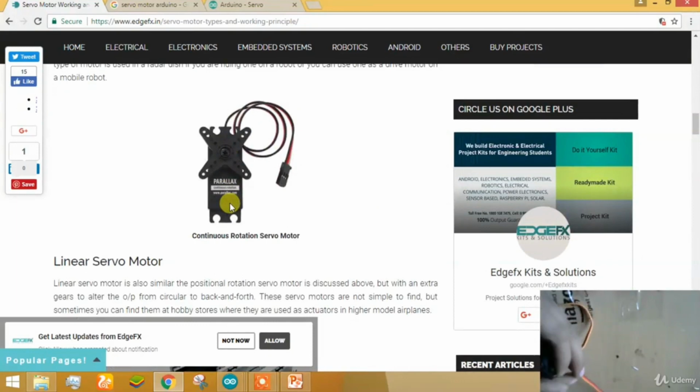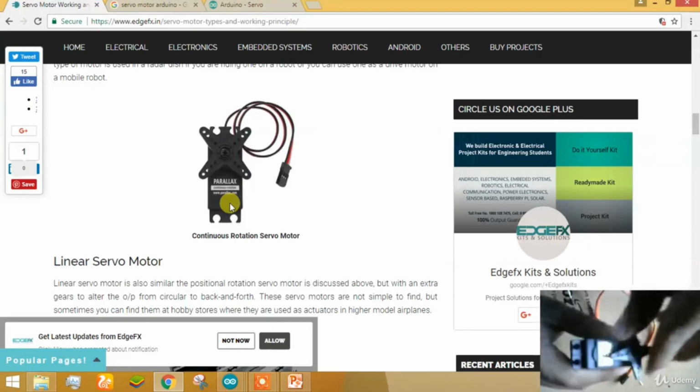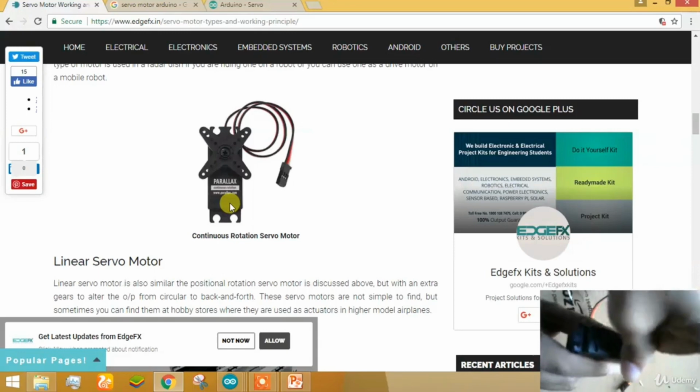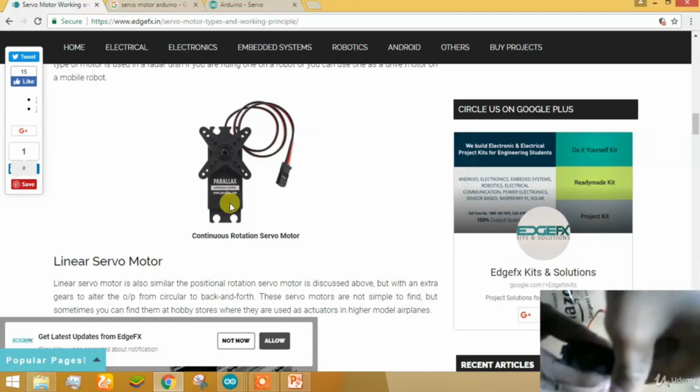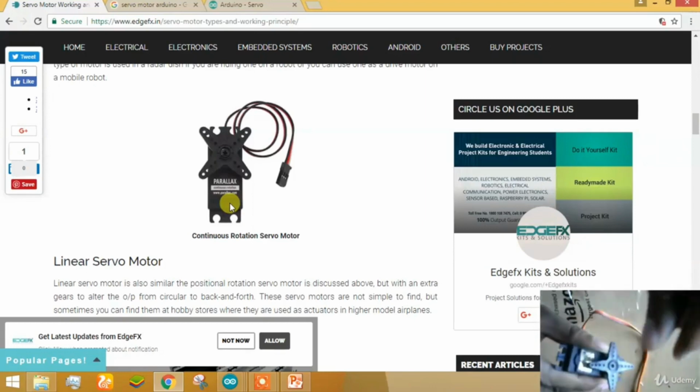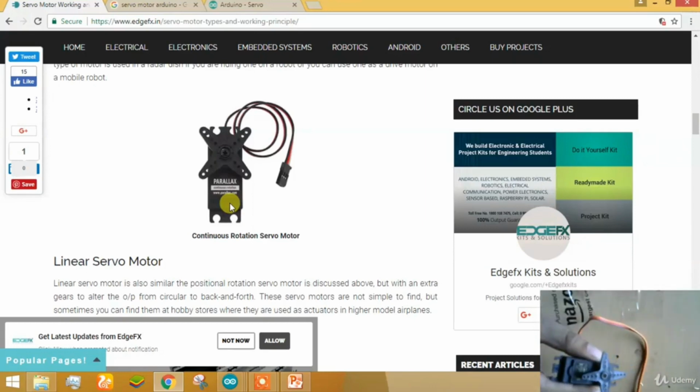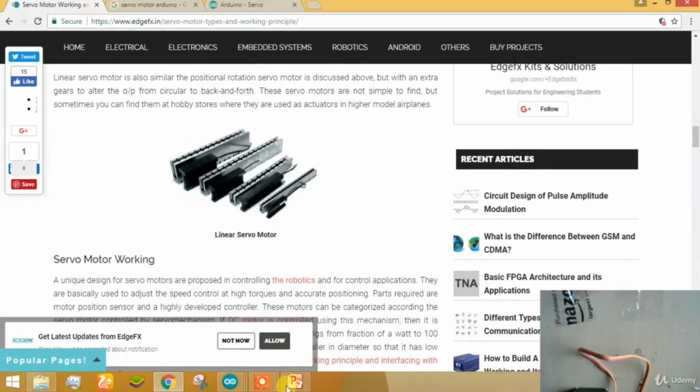It is called a continuous servo motor because it can rotate continuously 360 degree and can rotate many turns. You can see that it can rotate continuously. These are special servo motors that do not have the pin or the physical part that stops them from rotating continuously, and their potentiometers are of good quality so that they do not deteriorate while running continuously through 360 degrees. I think it is clear for us to get a complete knowledge of servo motor.